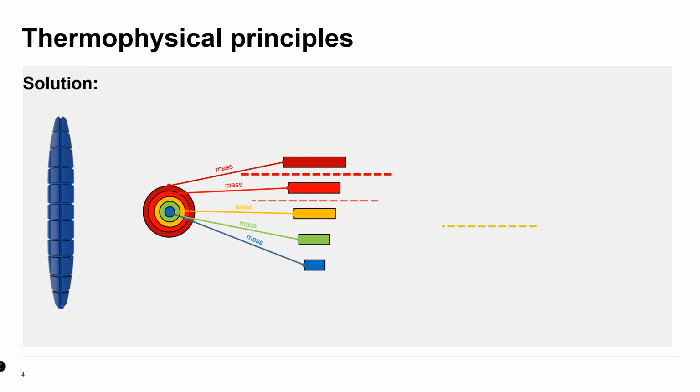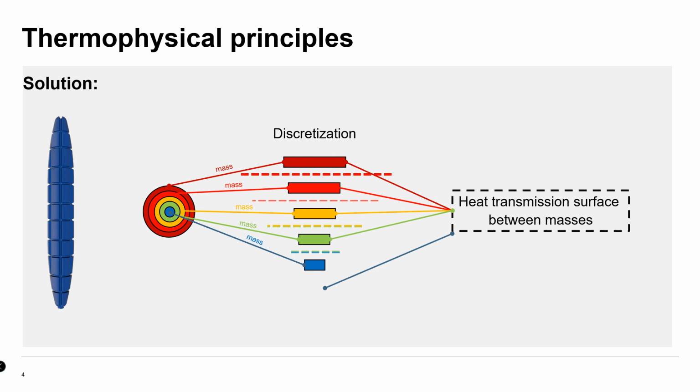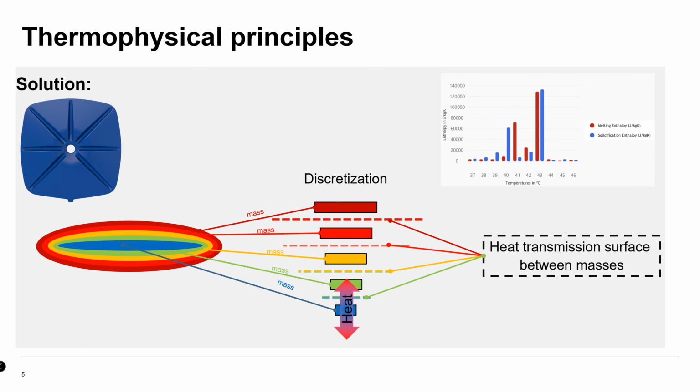Different masses of corresponding layers have adapted exchange surfaces to enable calculable transient heat exchange between individual layers. This approach can be chosen for various PCM objects. In doing so, the different approaches for layer masses and transfer surfaces can be calibrated by using measurements.